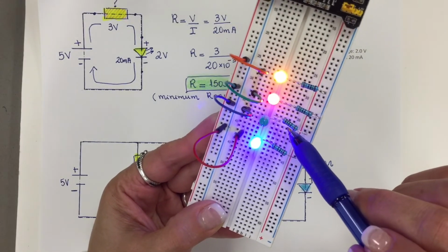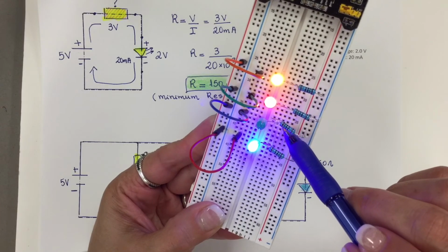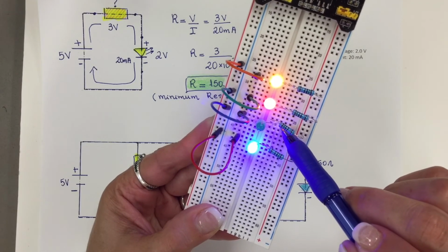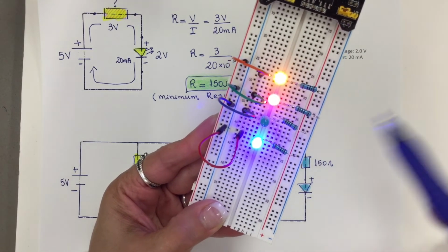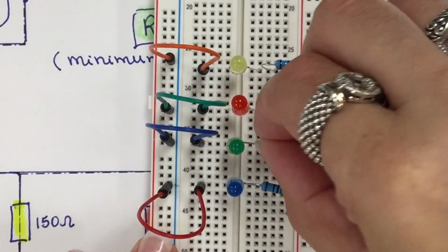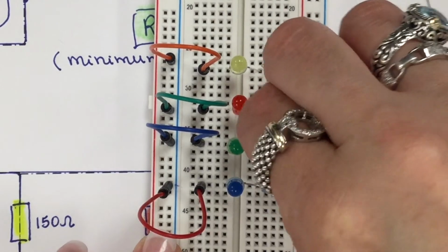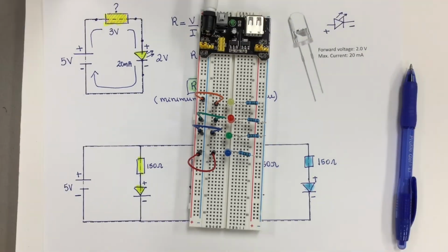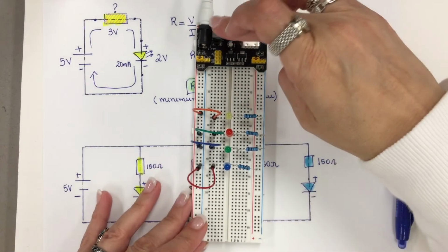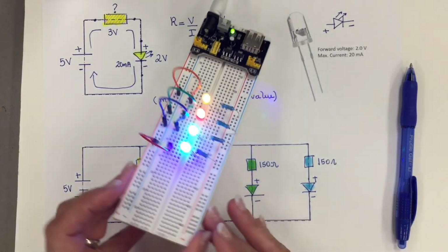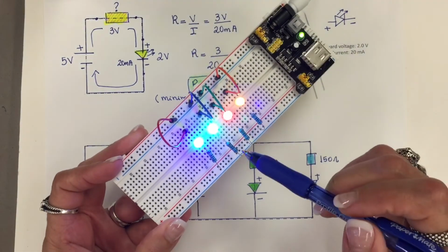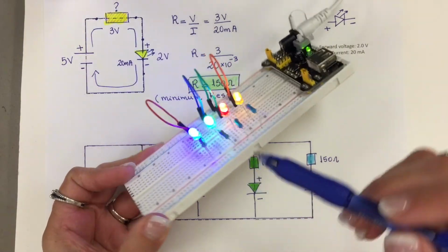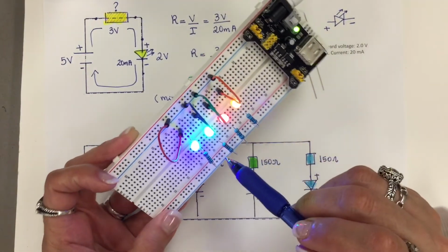So as you see here, the resistor is not in series with this LED. So I'm going to move this leg and make the correction. So this leg needs to go here. Okay, I moved it. And now let's test again. Perfect. So you see, a simple mistake like skipping a pinhole or connecting in the wrong location can lead to this type of problem.